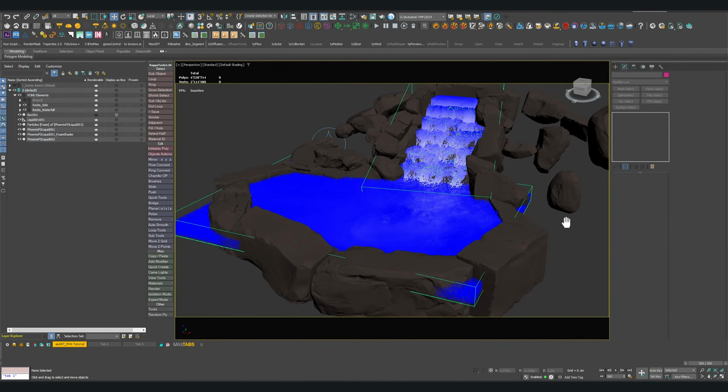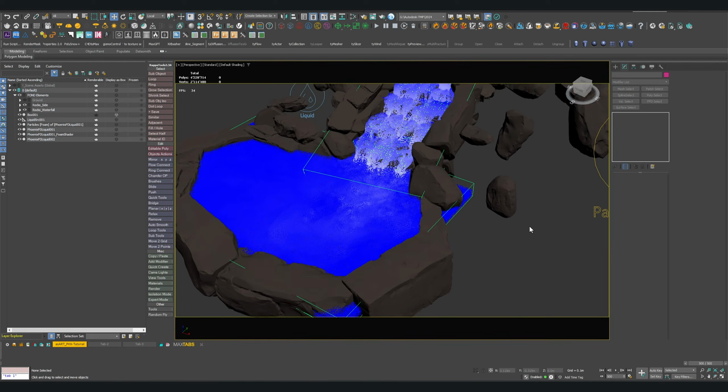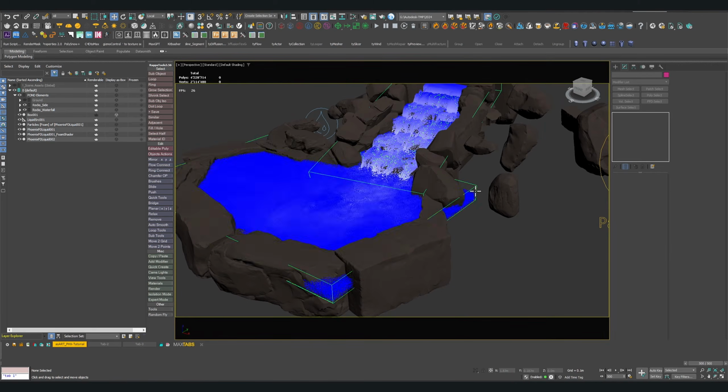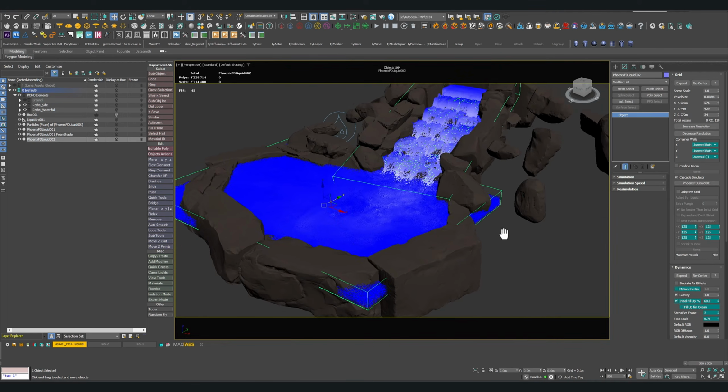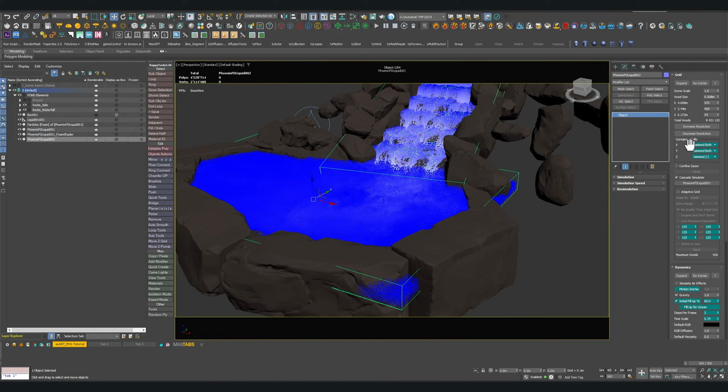So this is done now, but I changed some stuff during that simulation. First of all, I was setting the X and Y container walls to jam plus instead of jam both, and that caused my liquid to just disappear. For the z-axis, the jam minus is okay.